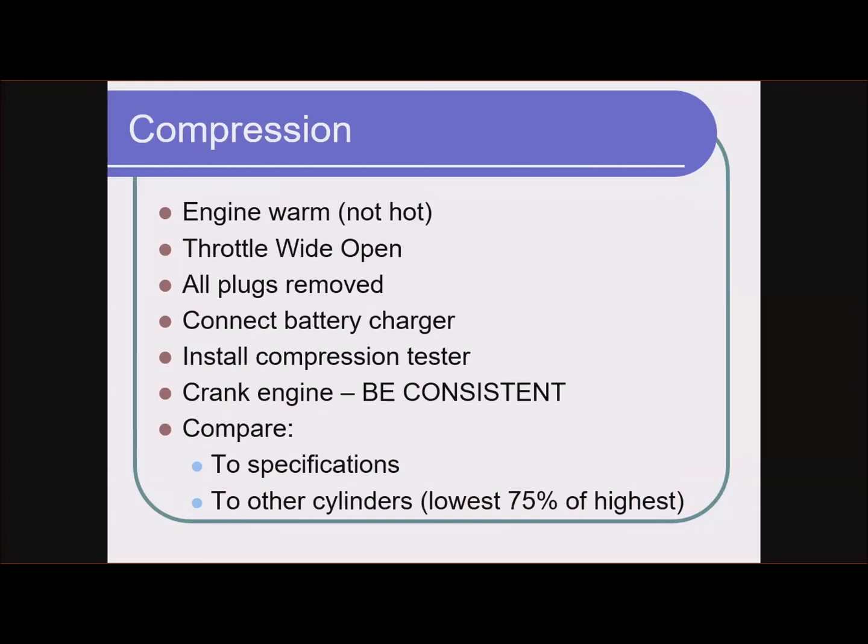I'd like to say that I can give you an exact number of how many engine rotations or how many compression strokes you should do on each cylinder, but I have seen some factory directions that say 5 compression strokes, some that say at least 5 compression strokes, and some that say until the gauge stops going up, so getting maximum compression. I guess this really is a function of how they came up with the specification they're giving you.